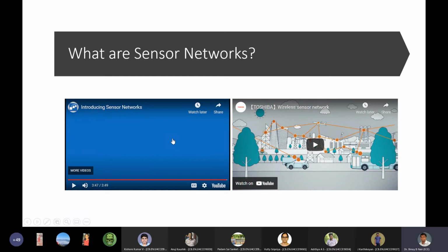Each device will have its own device ID. At the maximum, 512 devices will be connected. There will be one master and all others will be slaves. The master will tell which sensor should respond. Each of those units will be assigned an ID number, and one of them will act as a master and say that ID number 1 should now send the data, ID number 2 should now send the data, 3, 4, 5, 6.